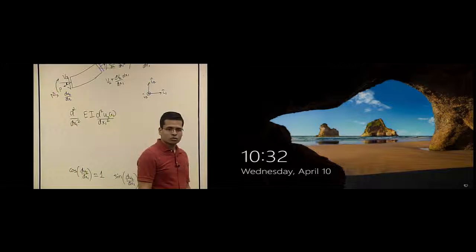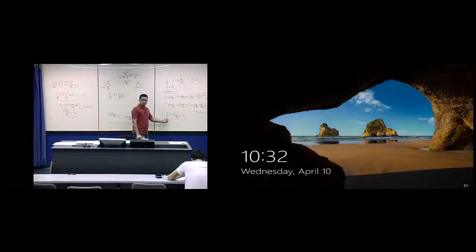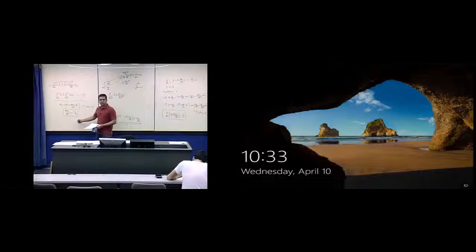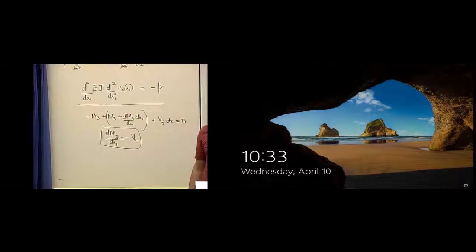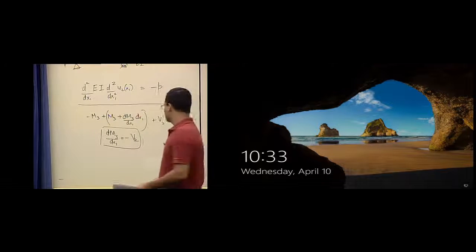So in this equation, the contribution for the moments, because now we're saying that they all have contributions in the two directions, wouldn't we also have to take their components and then multiply by like dx1 over 2 or wherever they're applied, or am I wrong? So we do that even in Euler-Bernoulli beam theory, right? When we do not have actual components, and we still get this equation, isn't it? You should check it out. No, I'm sure you're right. Thank you. I think it includes that, but they cancel out. Okay, so we're just not including it because they cancel out. Okay, thank you.